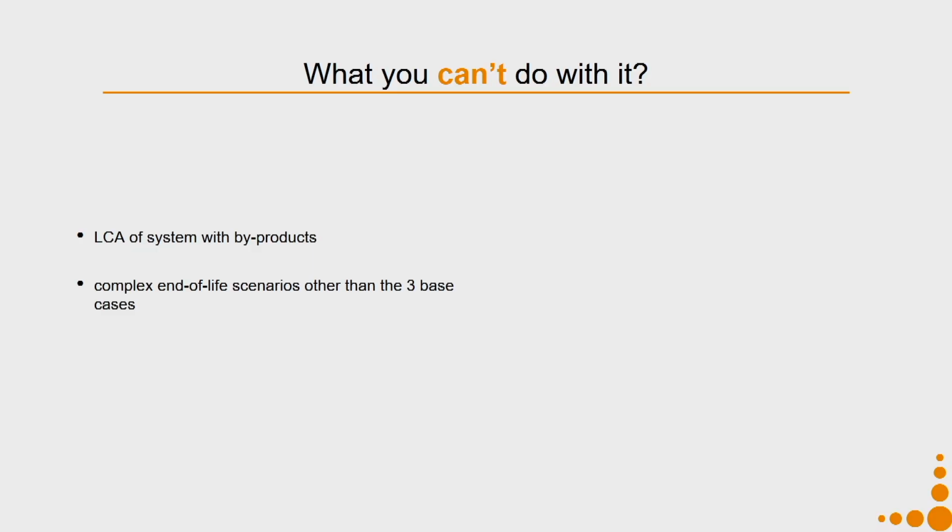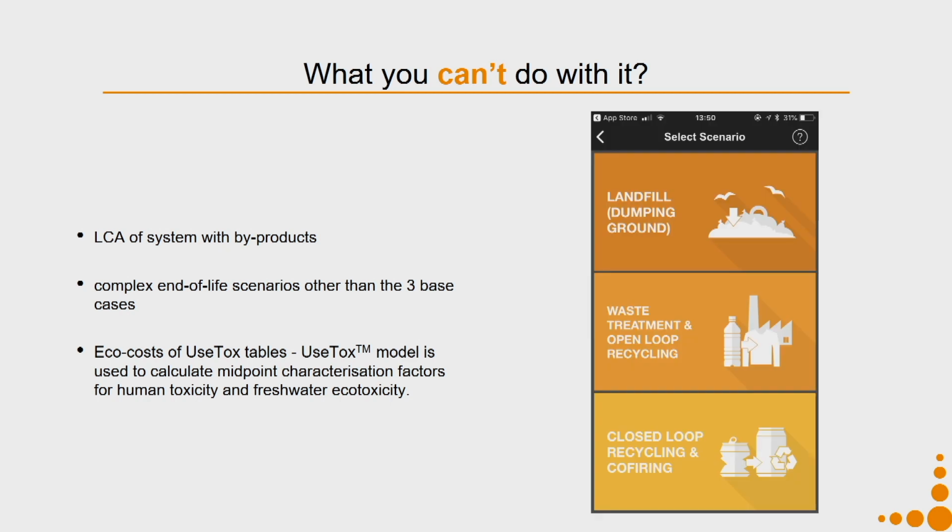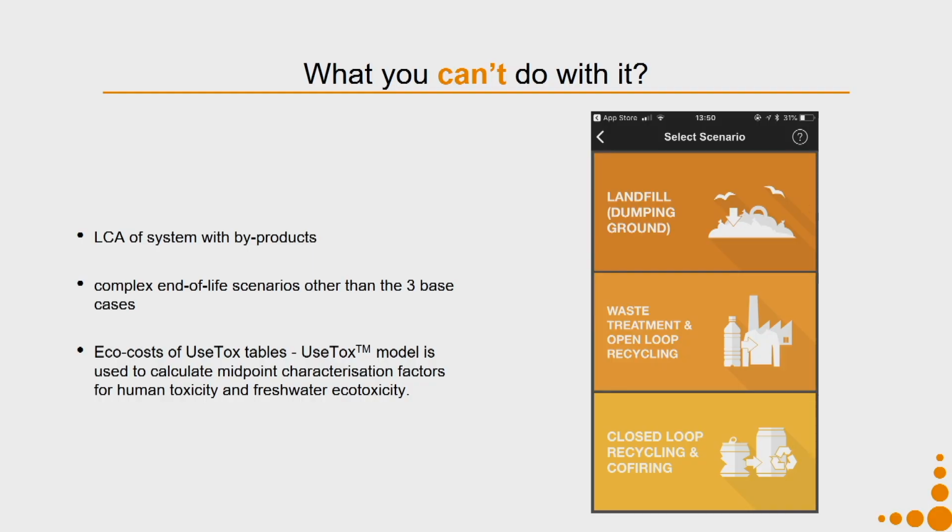You cannot do complex end of life scenarios other than the 3 base cases. The 3 base cases in this application are landfill dumping ground, or waste treatment and open loop recycling, or closed loop recycling and co-firing. So, these are the only 3 end of life scenarios for which you can do a life cycle assessment. You cannot do it for more complex scenarios. But in most design cases, when you are trying to design new products and solutions, the facility which is being given by these 3 scenarios is good enough.